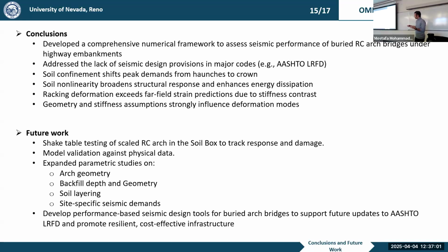What about the future work? As I told you, in the experiment phase, we are going to do shake table tests and verify our numerical models. So we will have a validated framework to test different geometries only by simulations and get decent results. I'm going to do some expanded parametric studies on different arch geometries, cross-section geometries, and different reinforcement details.